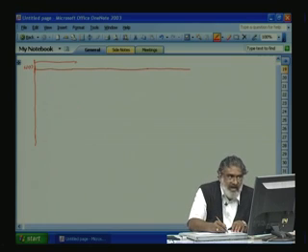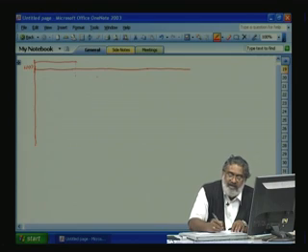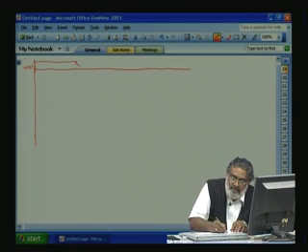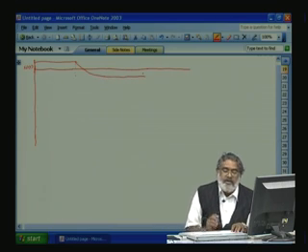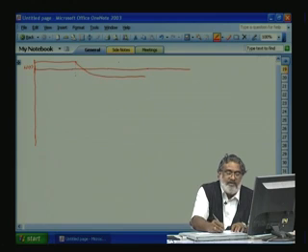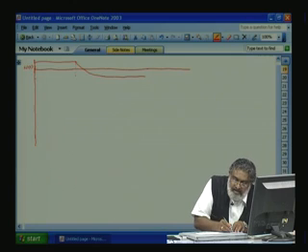So, from here ideally it should go quickly, but this is not possible, this is a step change. So, the response is a first order lag with mechanical time constant, it should slowly go and come to the required speed like this and stay there. You should not have a transient like this, it should go smoothly, our controller should take care of that. This is our final speed. So, what will happen to the current here? Let us take the current axis here, armature current.